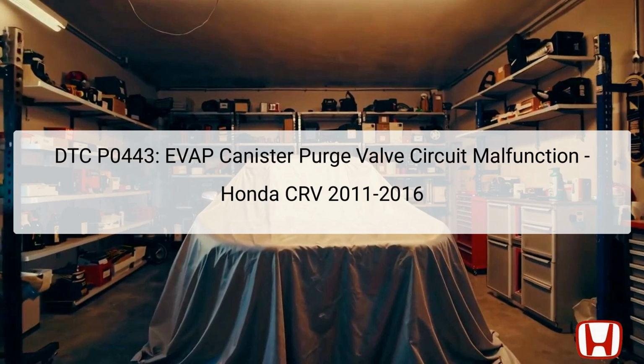The primary component in this system affected by the code P0443 is the EVAP Canister Purge valve, located in the engine compartment. When the engine control module, ECM, detects a fault in the circuit of this valve, the P0443 code is triggered, signaling that there could be an internal issue with the valve itself or in the connections leading to it. Understanding and resolving this issue is essential for ensuring vehicle compliance with emission regulations and optimal engine performance.